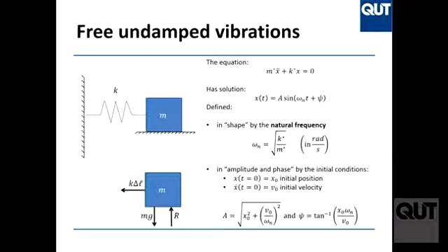purposes, and you don't want the vibration to be big enough that it creates a rubbing between moving parts and static parts. So that's why amplitude is interesting in that case, obviously. You want to know if the amplitude of vibration is bigger than the gap you have, because if it's bigger, that's big trouble, it's going to hit. Good.